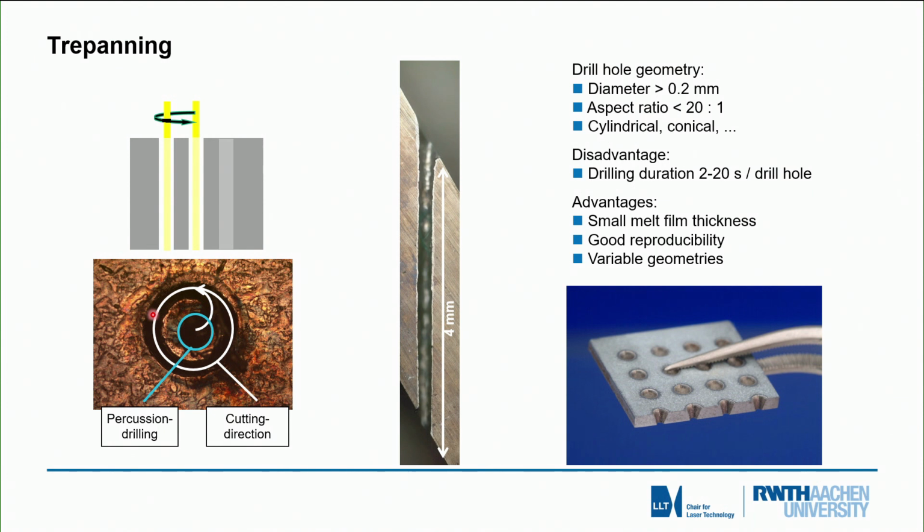So with this process, we can address also geometries under rather narrow angles. This can only be done with difficulty by mechanical means. So in this case, we have the opportunity to drill holes also under rather large angles of incidence. And we also can make conical holes, as you see in this example here, depending on the way how we now guide the beam in space with this additional axis. A very flexible way of drilling holes.